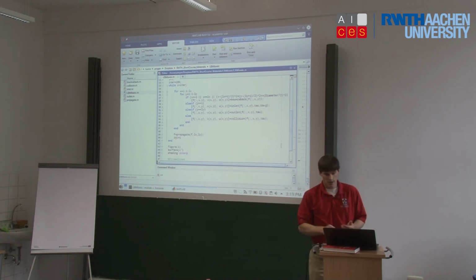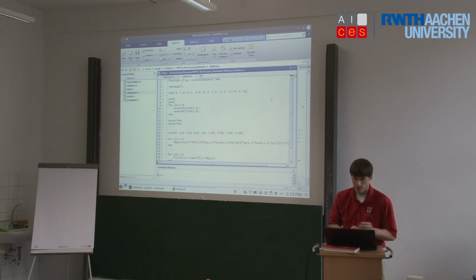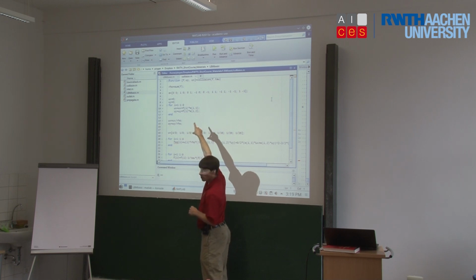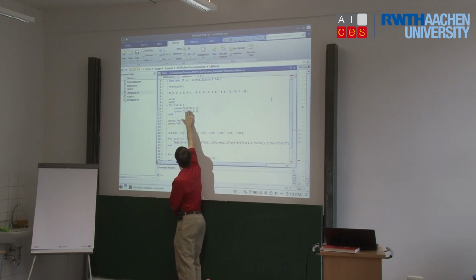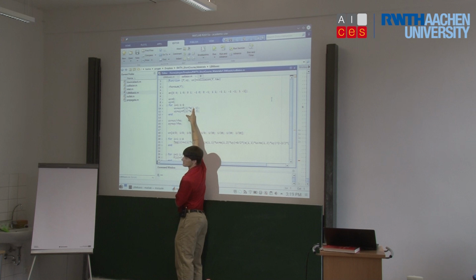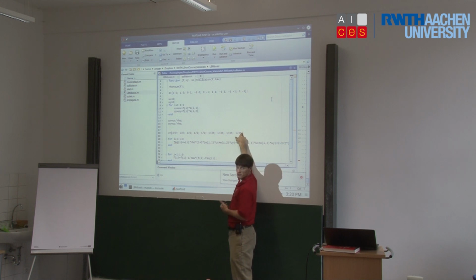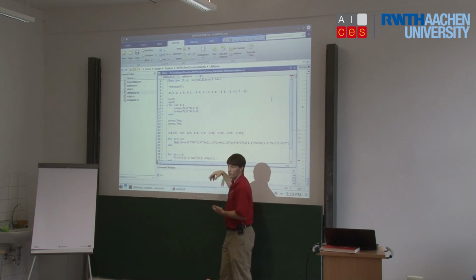So what the collision step does is, if I open this up, it calculates the macroscopic properties. The density is just the sum of all f values. Then it calculates the momentum, which is really f times the velocity in the x direction is the ux momentum, and f times the velocity in the y direction is the uy momentum. And then here are the weights from the Gaussian quadrature, and here it calculates this equilibrium distribution function, and then right there we perform the collision step.